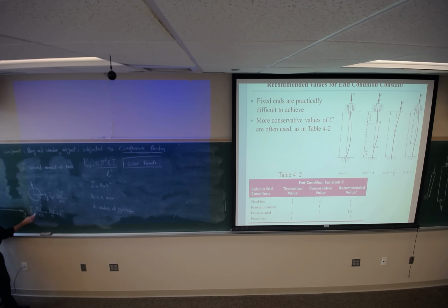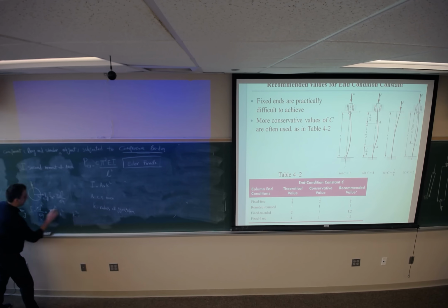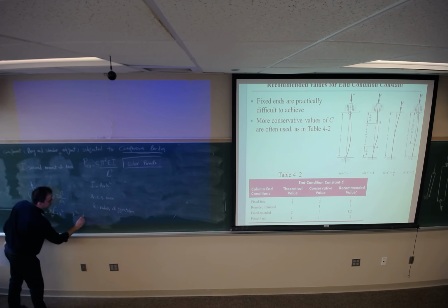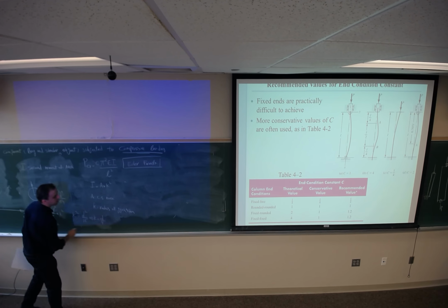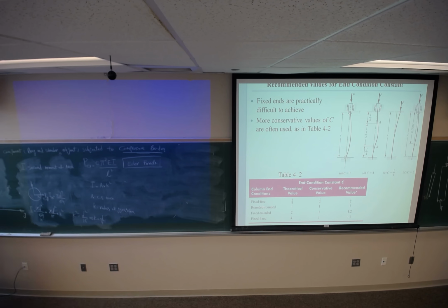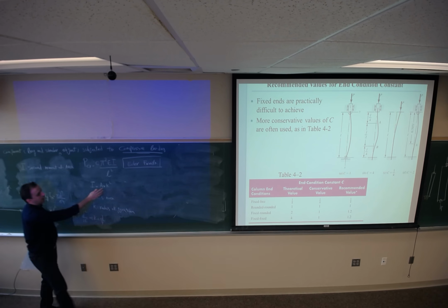So I can cancel out pi, and k squared is going to be d squared divided by 16, or k is d over 4 for a circle. For a different cross section, you will find a different radius of gyration.